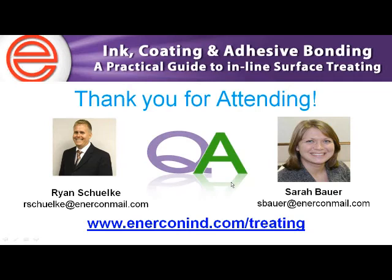That's a great question. I would love to say yes, but that's not the correct answer. Dyne level is really only an indicator for adhesion. It's only an indicator in the sense where we can see how we are changing the surface energy of the product that's being treated. That being said, there are cases out there, it's less common, but it does happen, where we either, one, don't see a change in dyne, or two, we do change the dyne. If we don't see a change in dyne, the customers sometimes can still get good adhesion. If we do change the dyne, sometimes they don't get good adhesion.